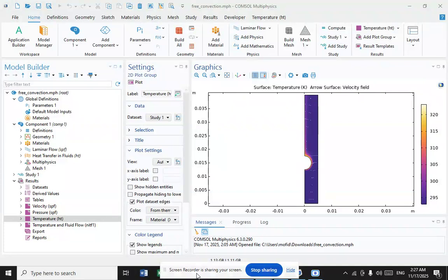External flow issues can be modeled using the classical boundary layer theory, assuming that the area outside the boundary layer is not affected by solid boundaries. Depending on the type of thermal boundary condition used in internal natural convection problems, there are two categories. The first one is cavities whose sidewalls are heated or cooled, in which case the temperature gradient is perpendicular to the direction of gravity acceleration.